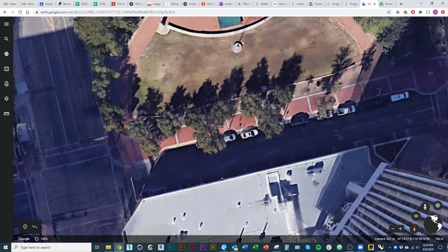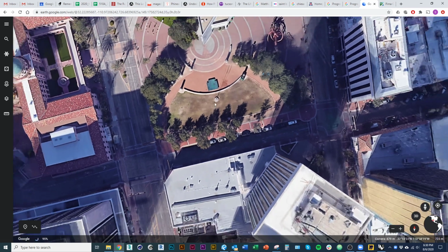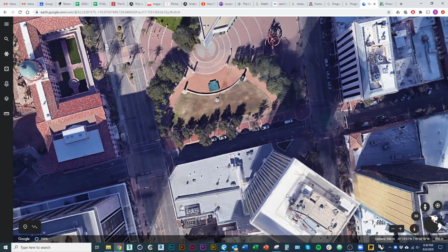You can see that we actually can get the relative heights of objects from this viewport. If we look down in the very bottom right of our viewport, it's saying 766 meters. And you'll notice when I move my cursor around, that number will change. So we can see that right there, there's a difference of 7 meters between the street height and the height of the building. We move the cursor to the top of the skyscraper, we can see there's quite a bit more difference. So you can actually measure to a decent enough degree of accuracy to show things like context. You can measure the height of a building.